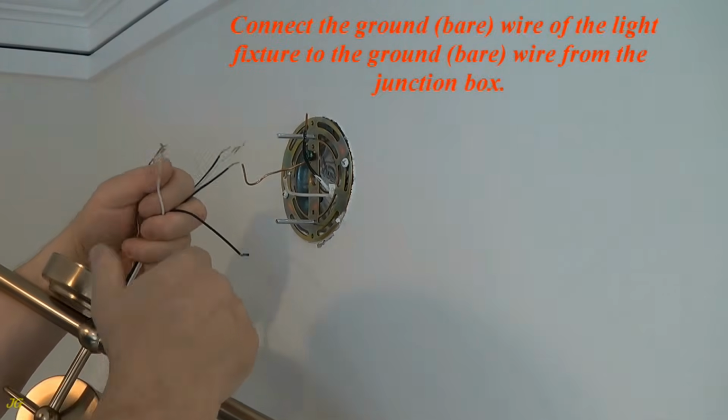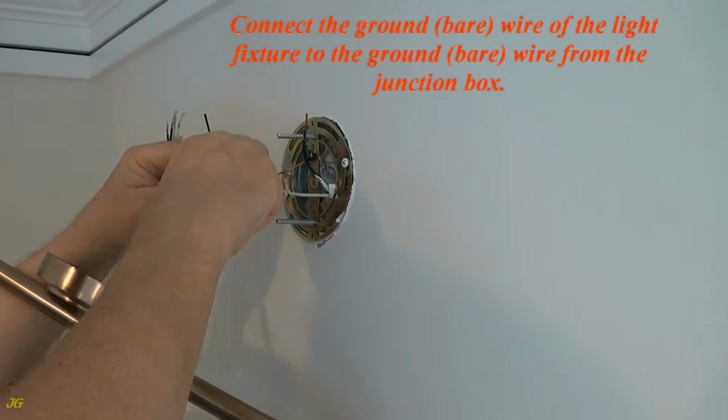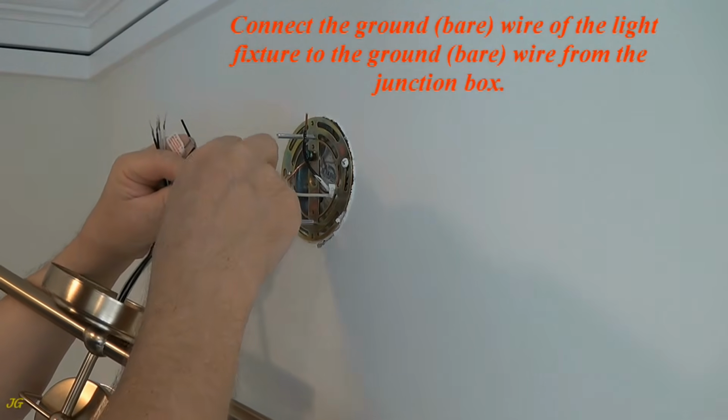Connect the ground, bare, wire of the light fixture to the ground, bare, wire from the junction box.